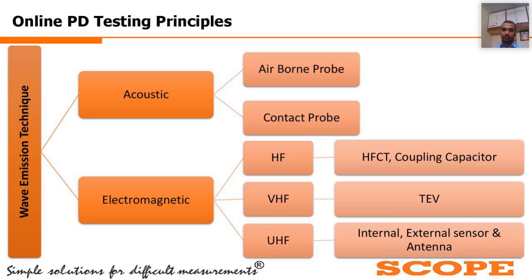These are the CTs that capture waves or the signals coming out of your equipment at a very high frequency. So they are not your regular CTs that work on the system frequency. Second one are the coupling capacitors. You can say they are bushing sensors of a miniaturized version, right? So they step down the voltage, because they are coupling capacitors. They also work in high frequency only, and they try to capture the signal or the PD current coming out of that particular terminal or point where the sensor is. Okay, and from the other terminal of it, you can take the reading.